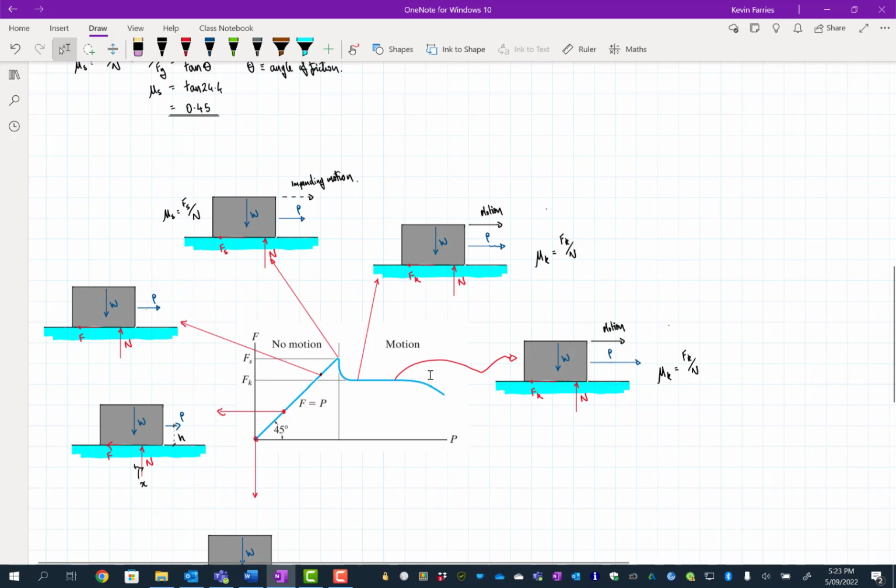It could also increase at the end, if it's been sliding for a long time, because you might wear off a low friction coating, or you might lose lubrication. And so it's possible that this graph goes the other way, up over time. And this is a little bit dodgy here.